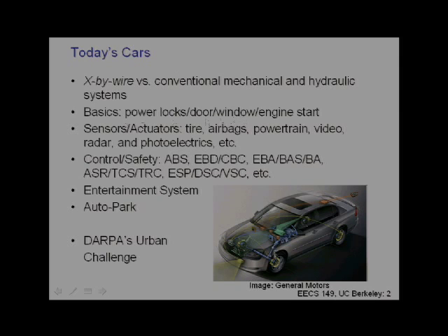Now, what are the things that are on the network in the car? So there's clearly different pieces of software controlling different parts of your car. There's also sensor units and actuator units, and they're all sitting on a bus, okay, and communicating on that bus. So CAN is a way of specifying the protocol that governs how they talk on that bus. Okay, and so the trend seems to be going more and more towards automation, right? And DARPA's Urban Challenge is sort of one extreme point where you don't have the human at all and you have autonomous cars.